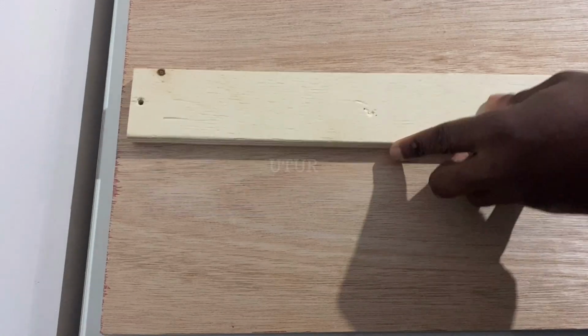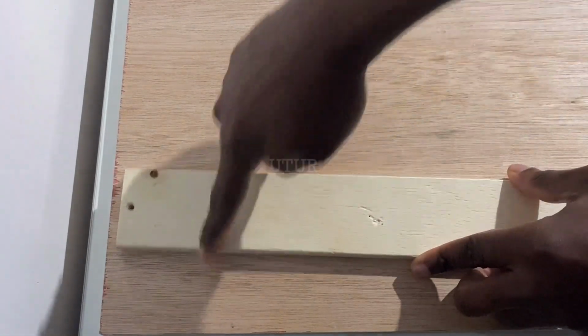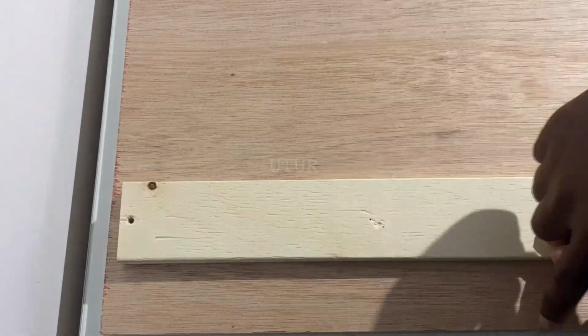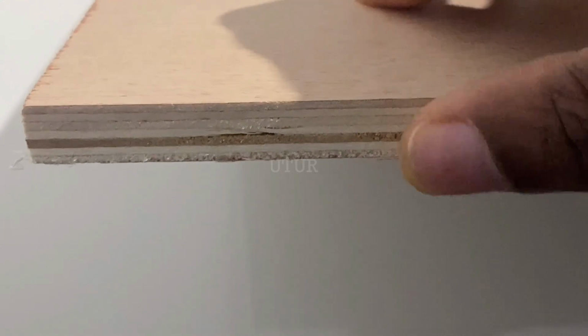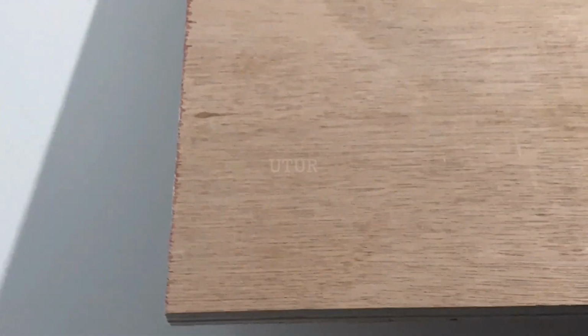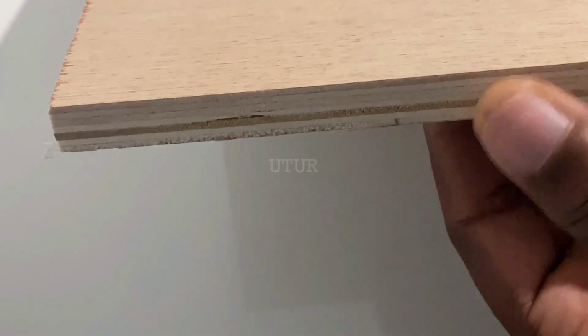But both the ripping blade and the cross-cut blade as standalones may not be the best solution to cut your plywood, as your plywood is a type of manufactured wood panel that's made by gluing veneers together. And as a result, there is a high propensity that the wood grain may be alternating on each other, if the veneer layers are glued with the wood grain of the plies at right angles to each other.